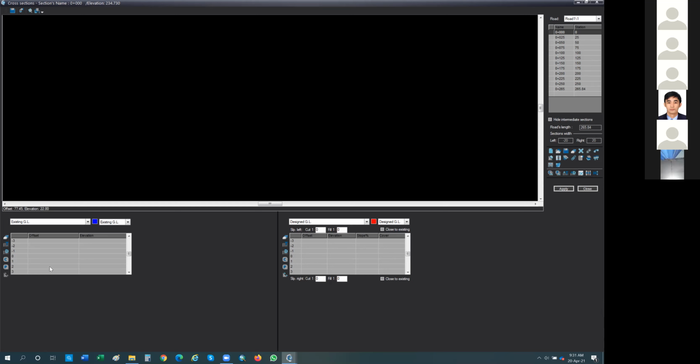Right? Yes. Now you want to cut the existing ground level. So press the Get Topo Data button, again on the right side, third to the left in the lower row. That's right. Good, excellent. Thank you. Yeah, press OK.